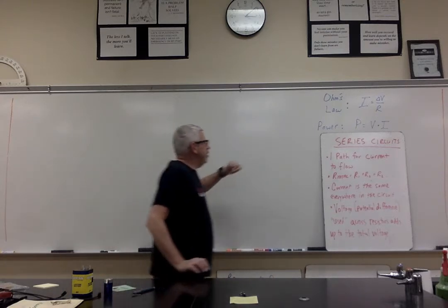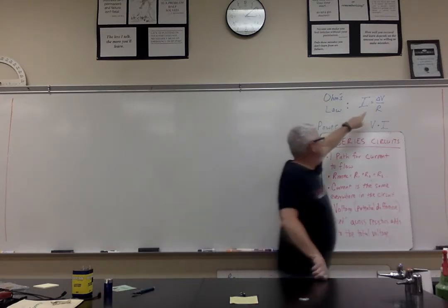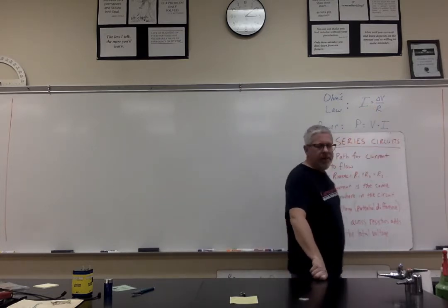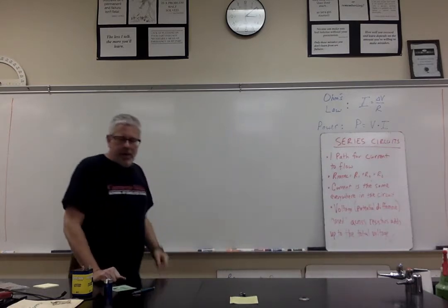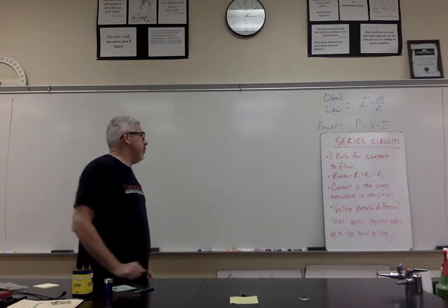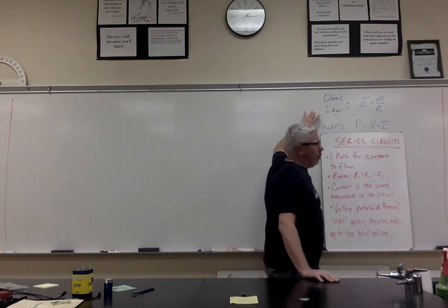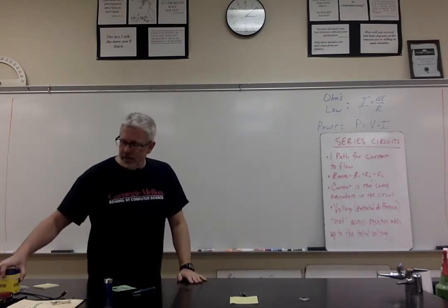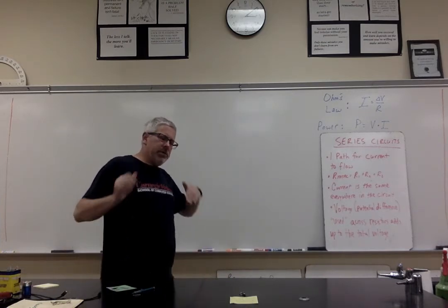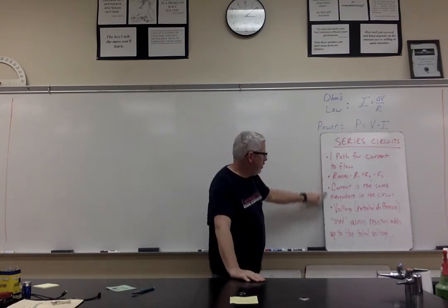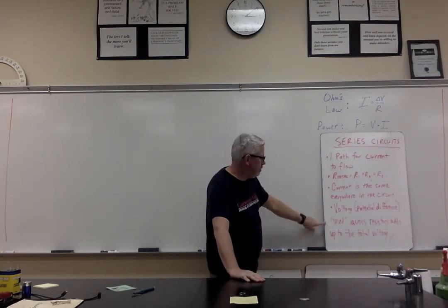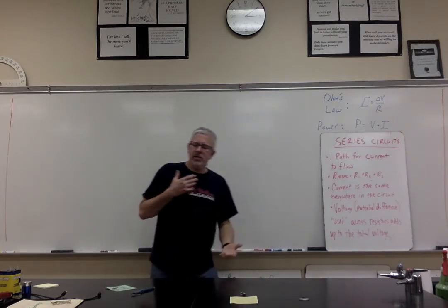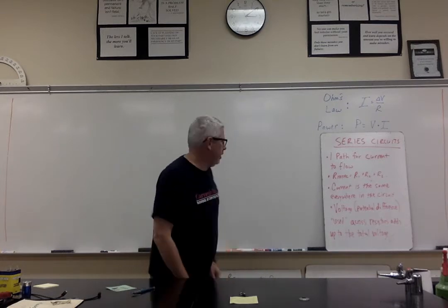And Ohm's law, which is I equals voltage divided by resistance, and the power formula, P equals voltage times current, apply to any part of this circuit or the whole circuit. That's actually kind of important. These formulas are pretty straightforward. They're not hard to use, but you've got to remember that they can be used in any part of a circuit or a whole circuit, as long as you're thinking about your logic correctly with how we solve for series circuits, and later on how we solve for parallel circuits, and finally how we solve for combined circuits, which have aspects of both series and parallel circuits.